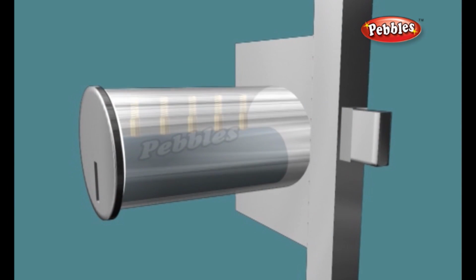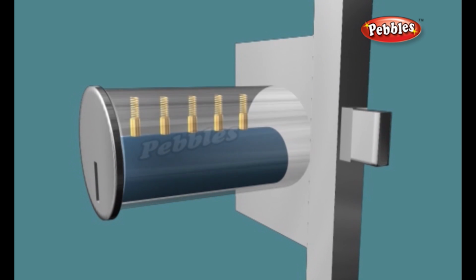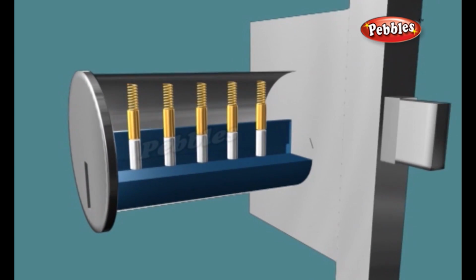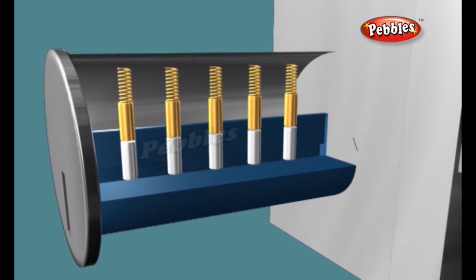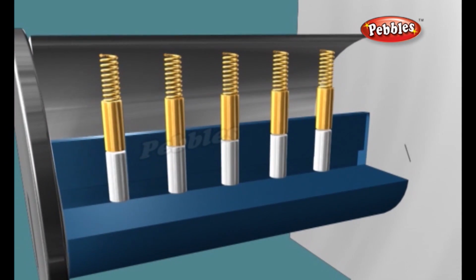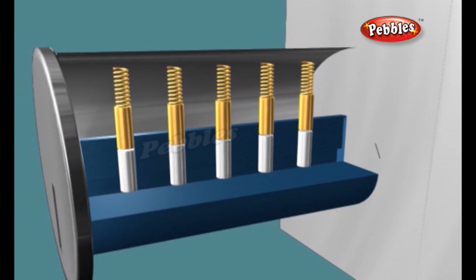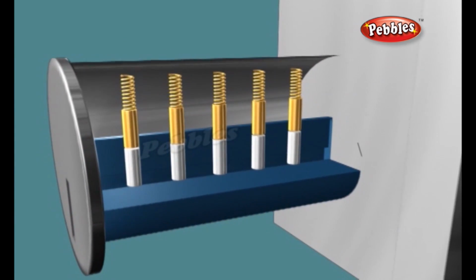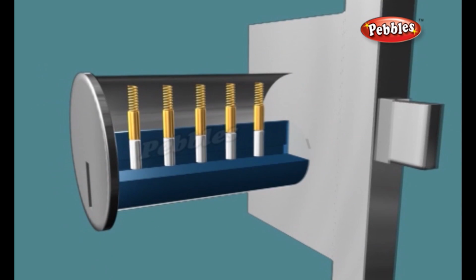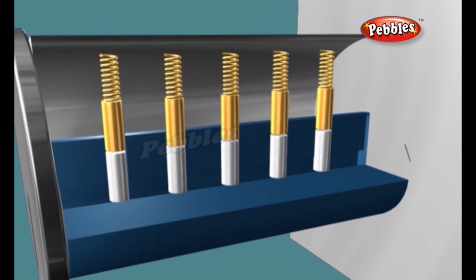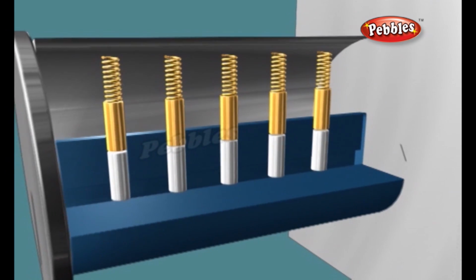The main components in the pin and tumbler design are a series of small pins of varying length. The pins are divided up into pairs. Each pair rests in a shaft running through the central cylinder plug and into the housing around the plug. Springs at the top of the shafts keep the pin pairs in position in the plug. When no key is inserted, the bottom pin in each pair is completely inside the plug, while the upper pin is halfway in the plug and halfway in the housing.